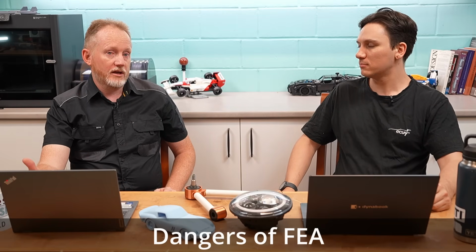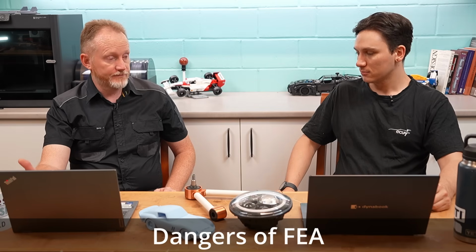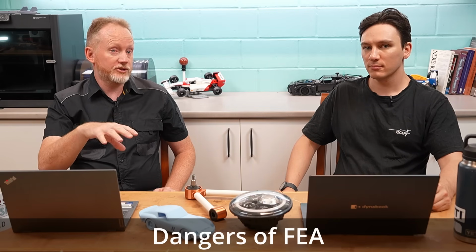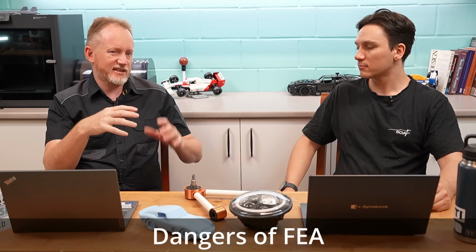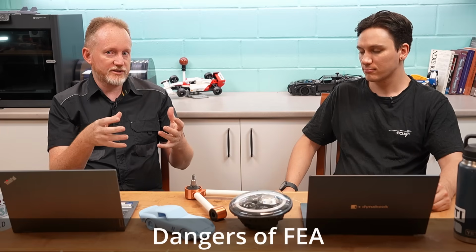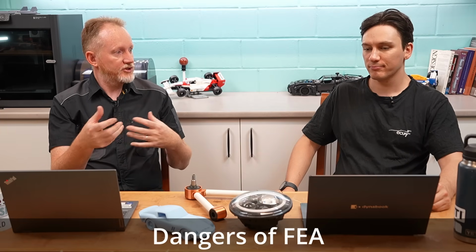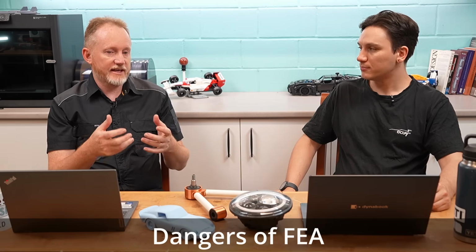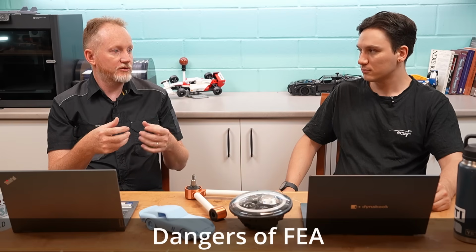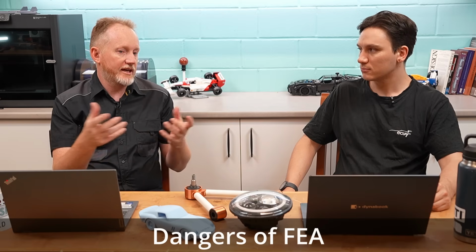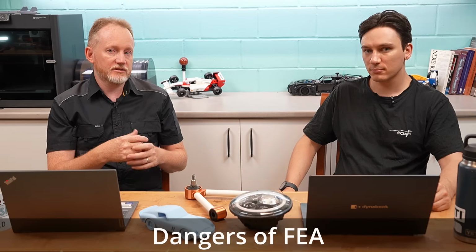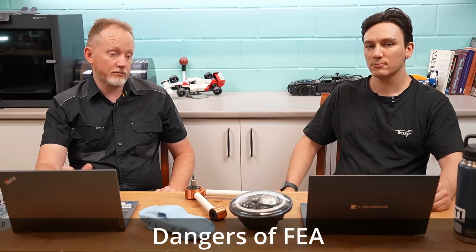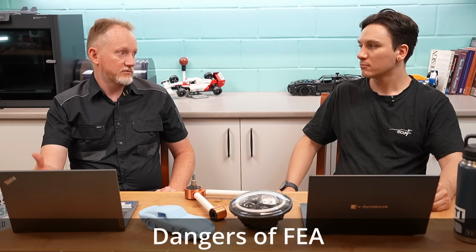So we were doing some brake disc design, and we're using a grey nodular cast iron. Most of the time when you're doing stress calcs, you're just looking at von Mises stresses. That's actually a combination of the overall stress. It doesn't give you an idea of what's in tension, what's in compression. And the issue with the cast iron parts is they can't be loaded in tension. So you need to be designing for compression, and we actually had an area that was under tension, and we got cracks. So all of those discs were useless. We had to redesign them, and caught it in time, thankfully, but it really caught us out.